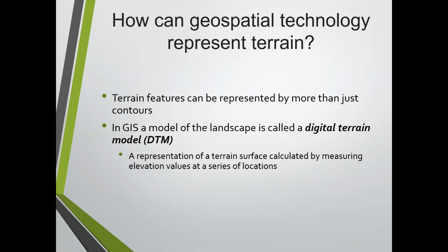A lot of you have done this out in the field and know that with a gridded site, where you're taking elevations every 25 feet in the X and Y direction, you're missing data. So most people use controlling points, where you're using center lines of swales, back of curbs, those kinds of things. You're getting that information and then incorporating it into somewhat of a grid pattern. But that's a different story.